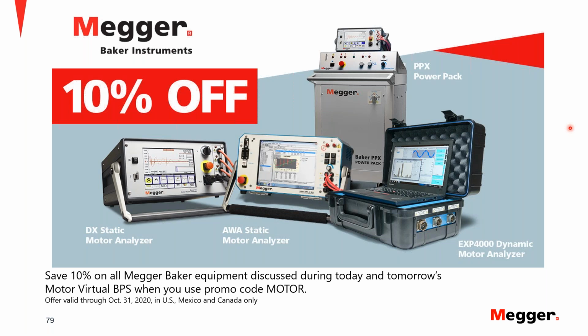That is the manufacturer's design where they were trying to hit, most often 40 degrees C. So the insulation class that's put into a motor has to do with at what temperature that motor is rated, and ambient goes in as part of that. So it's going to take the ambient temperature plus whatever temperature rise that motor has up to full load.